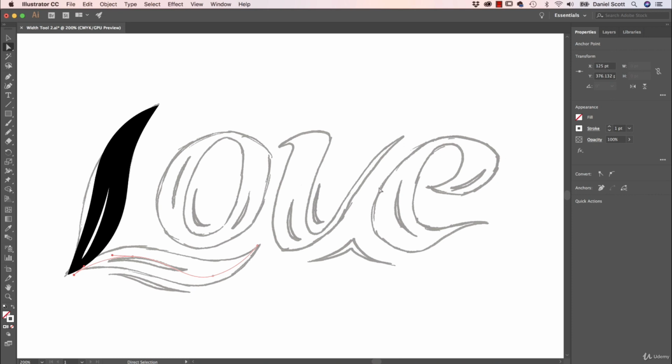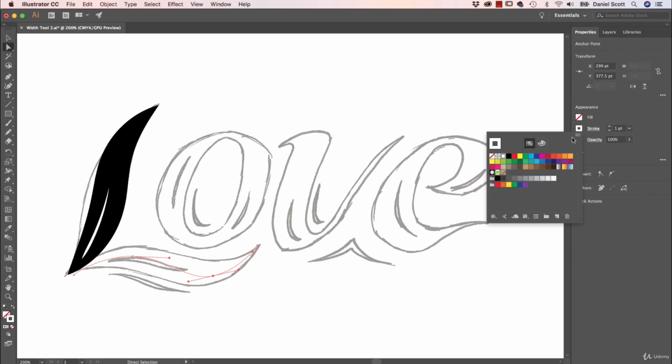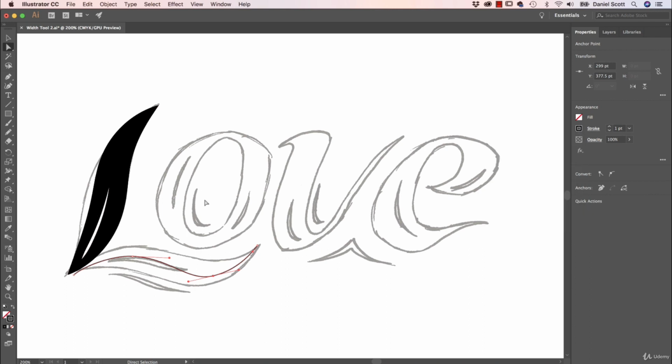All of these lines here. One little hint, I've practiced this already. I've taught this a few times. So let's change it back to black. The one thing that can catch people out is this O, and I only learned it through practice as well. How many points does it need? It looks like it needs about four. Turns out it works out nicely. Click once, click twice, click again, click again. You get this kind of boxy circle, and it's close to what we want.